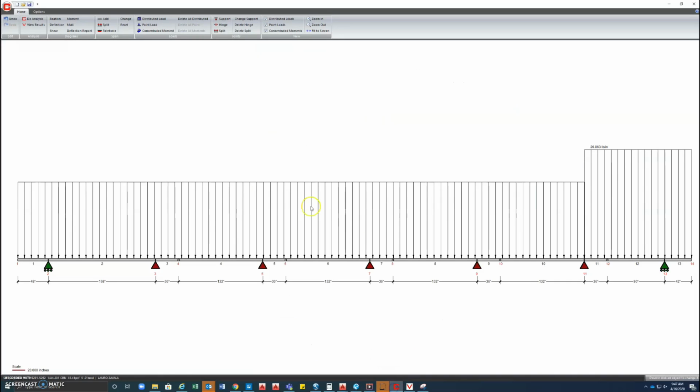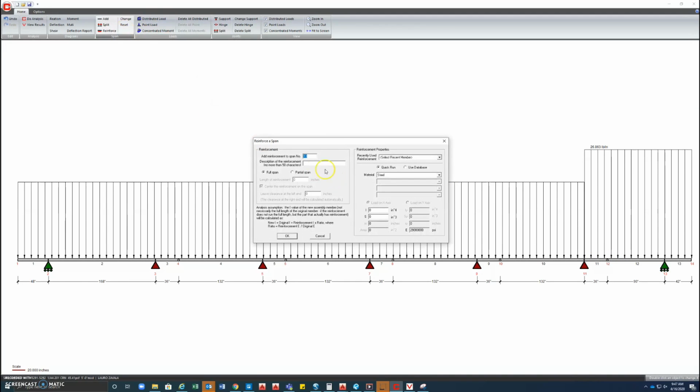Also, something to keep in mind, you can use special ASCE exceptions like taking tributary area pressures to reduce your loads if passing a particular system is absolutely required. If this is done, please notify sales and the structural engineer before kickoff.